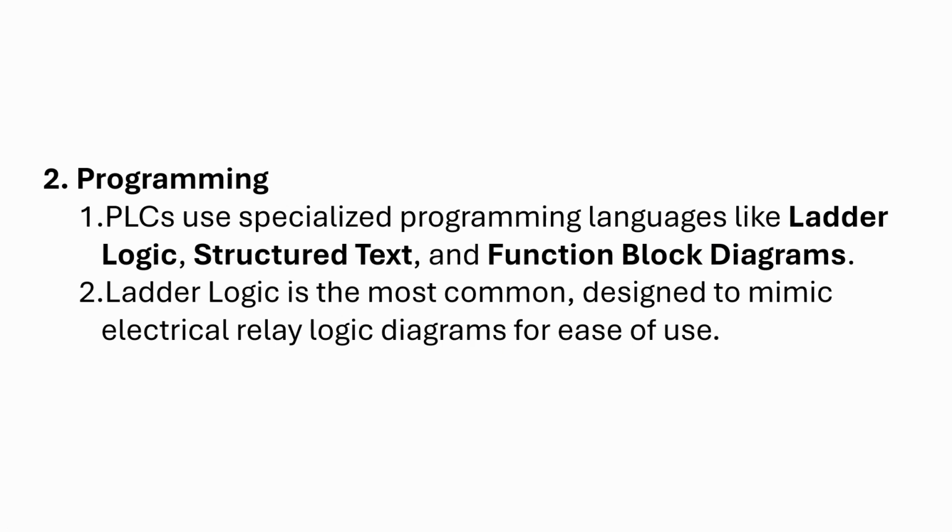Now, for programming, PLCs use specialized programming languages. A common one that's been used for many years is ladder logic. That's actually what we're going to be focused on here in this class. But there's also structured text and also function block diagrams. Ladder logic's still the most common, and it's designed to mimic electrical relay logic diagrams for ease of use. Back in the day before PLCs, you might find old control enclosures full of relays, just hardwired relays. And so PLCs have been able to replace these very large relay control systems.